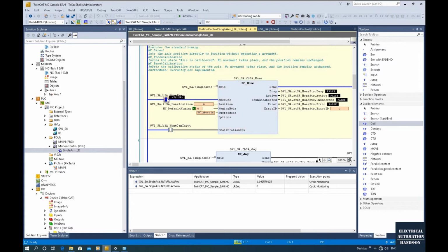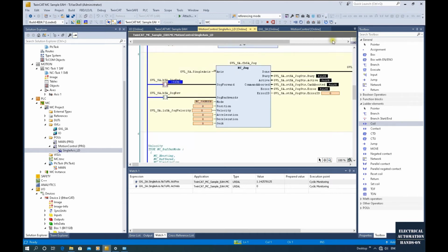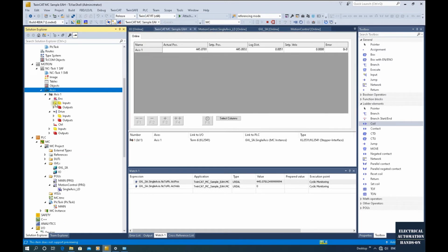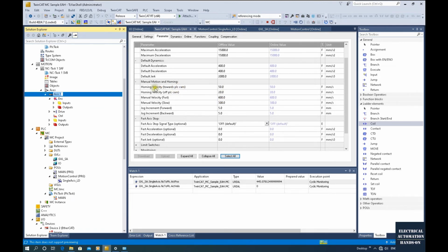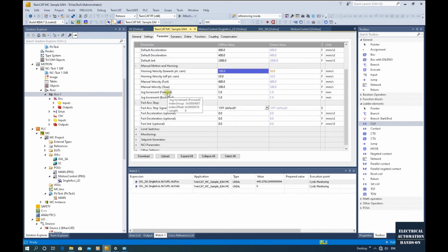So now I'm going to release here, and let's travel to someplace else and stop there. And this time, let me change the speed. For example, if I go to the axis, let's change the searching speed to be faster. For this searching home sensor speed, let's go faster, for example, 100. And for the PLC cam, that means going in the positive direction, leaving that home sensor, that's a 20.